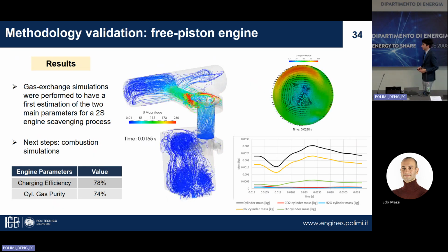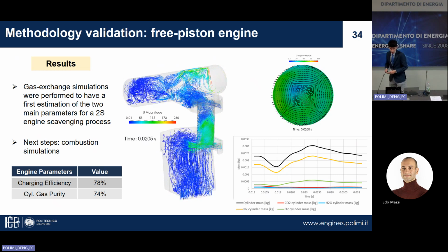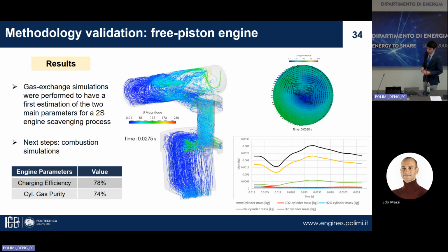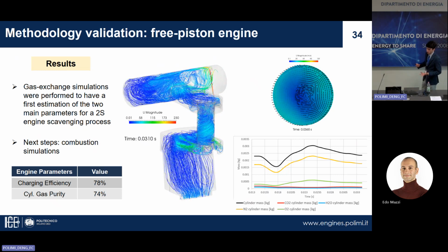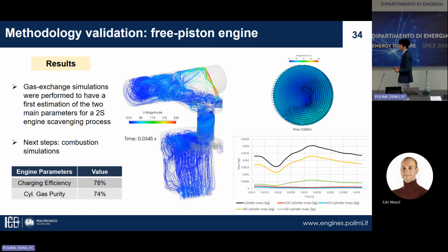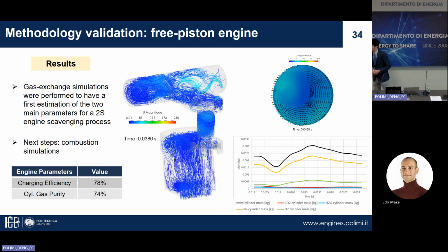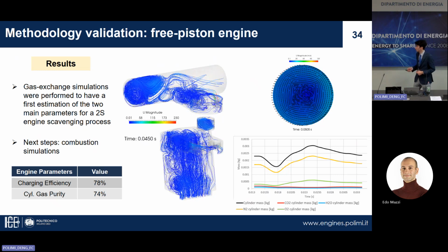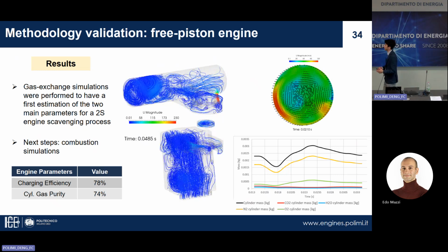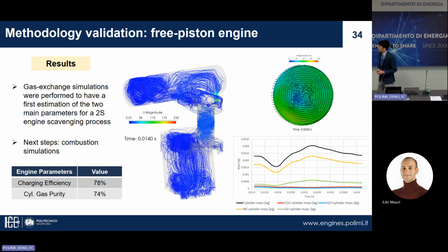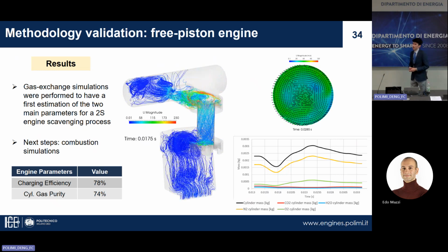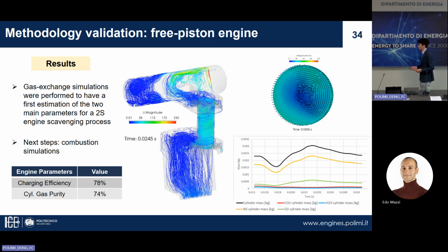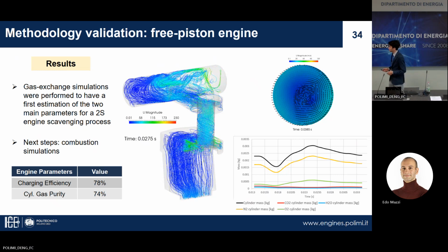We started a validation also on this type of engine. At this stage, only gas exchange simulations were performed, and two important parameters for this type of engine were extracted, the charging efficiency and cylinder gas purity, and they were in line with this type of engine. And then, of course, the next step is to perform some combustion simulation on this type of engine.